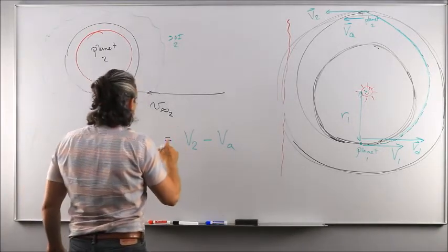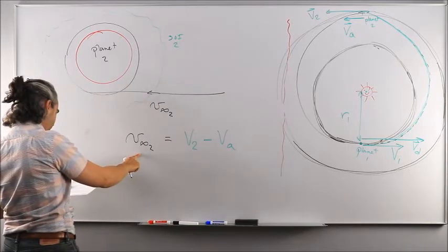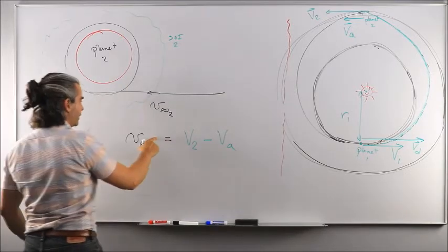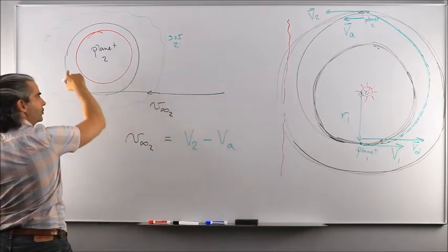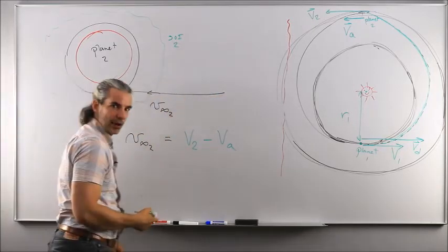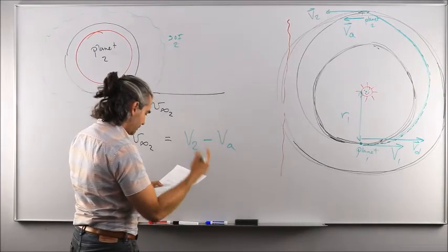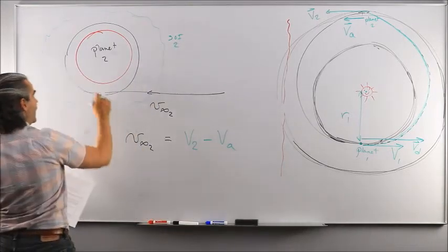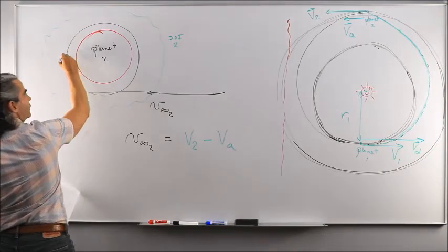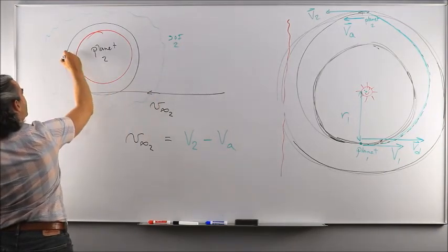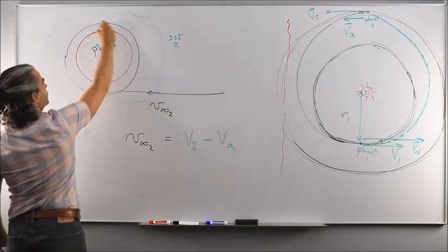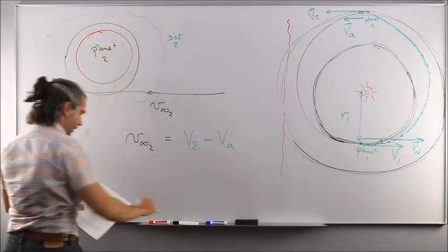And then from this, you could do the exact same thing as before, and that is to relate this V infinity of this hyperbolic arrival trajectory to its semi-major axis, and then to its speed at the perigee of this hyperbolic trajectory to figure out the delta V needed to slow you down to enter a capture orbit. Okay?